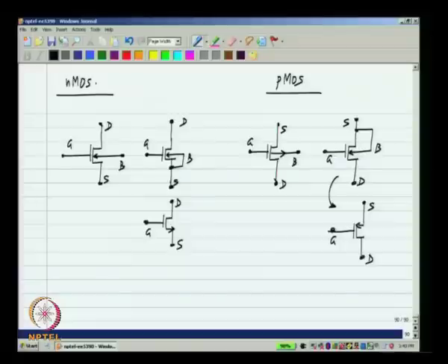Now, what does it mean for the transistor to be in saturation or in triode region? First of all, in the normal operation of the transistor, I will use the 3 terminal symbol for simplicity here. There will be a VGS which is greater than Vt. I do not necessarily mean that there will be a voltage source connected between gate and source, but whatever is connected will establish a VGS that is greater than Vt.